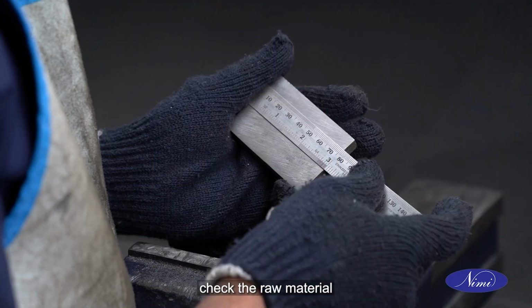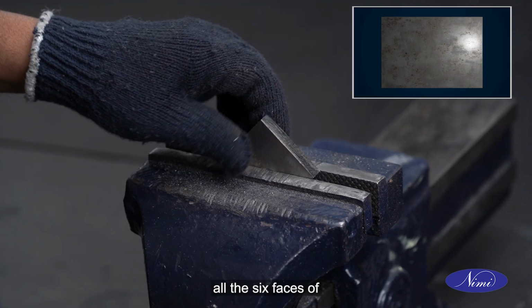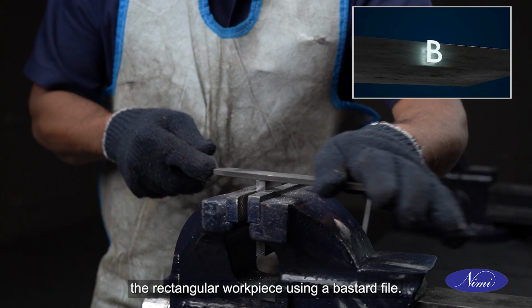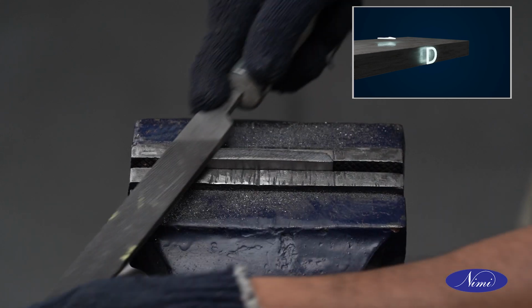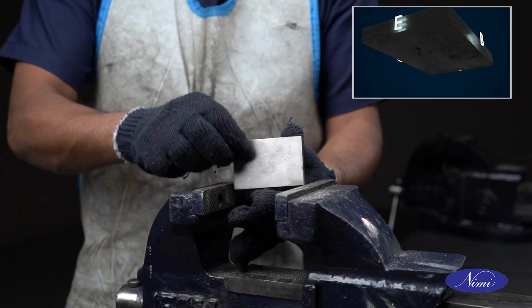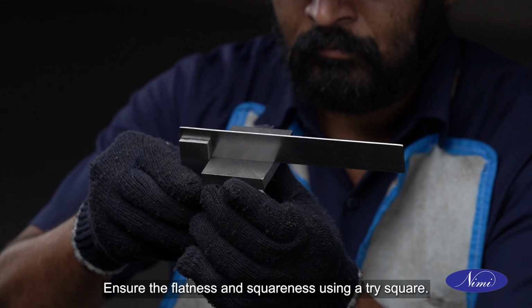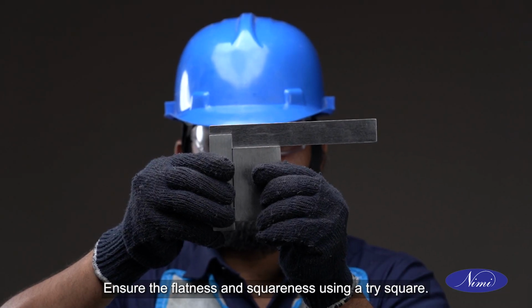Check the raw material for its size using a steel rule. Rough file all the 6 faces of the rectangular workpiece using a bastard file. Ensure the flatness and squareness using a tri-square.